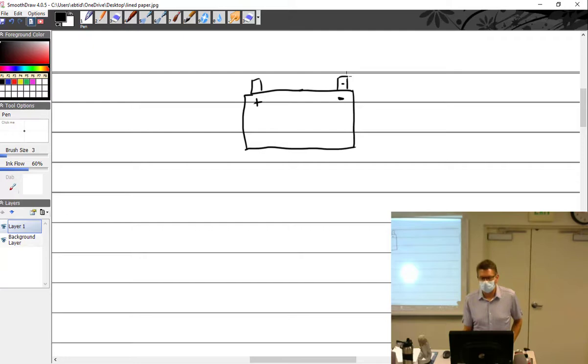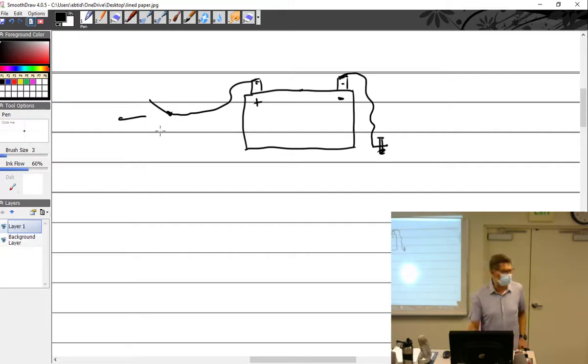So now, of course, in an actual airplane, we've got a ground strap that's going to be bolted right to the airframe. So we got a little bolt that goes right through there and a little nut. And so there we go. We have the positive, and we're going to have big old fat wires going all the way up to a master switch somewhere. And so we can disconnect almost everything from the aircraft.